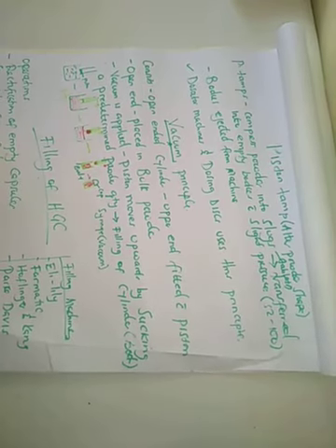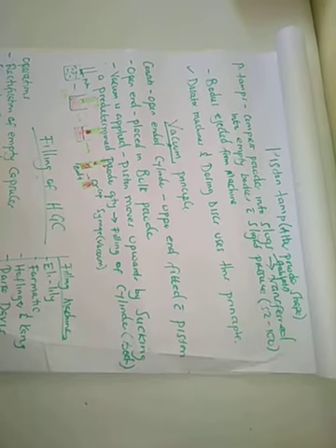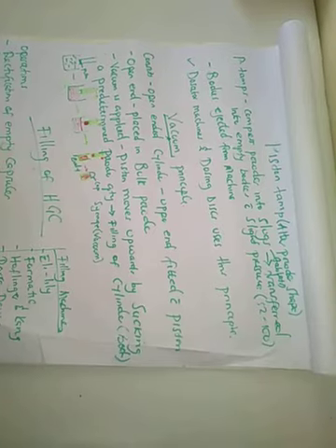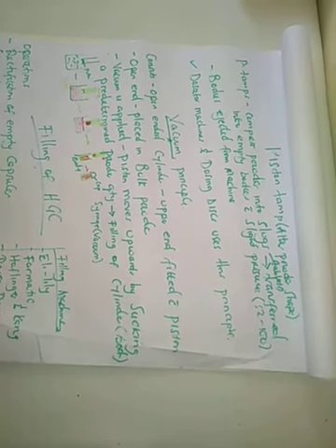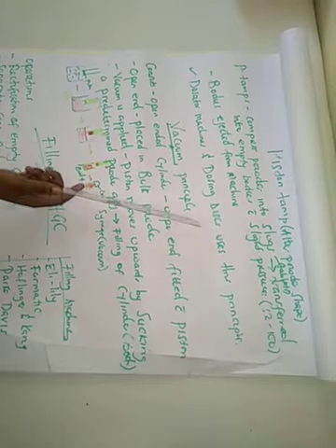The most important thing to note about the piston principle is that it alters the shape of the powder. It's not the powder which is filled into the capsules on its own. First, the piston tamp has to compress the powder into slugs, or tablets, or compact masses. Then these compact masses are transferred into the empty bodies. After that, they're ejected from the machine, and the caps are placed over. For example, dosator machines and dosing disc machines also use this principle.